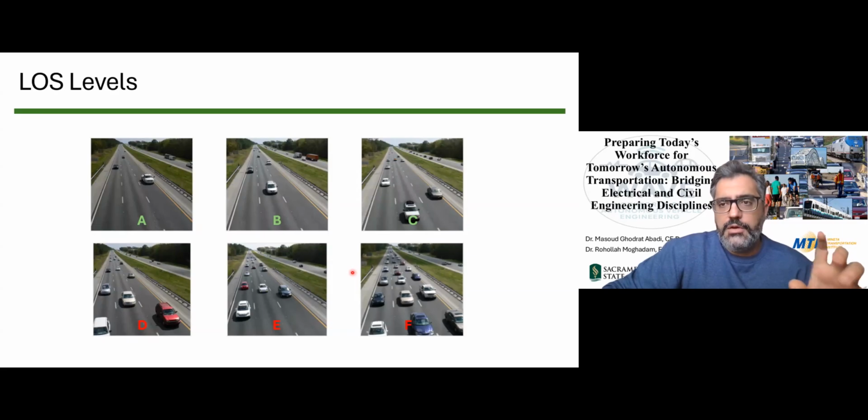With a minor interruption in traffic, like if you are at level of service E, you see lots of vehicles on the roadway, but still the system does not have major queuing. Then suddenly a driver changes their lane, or there is a distracted driver. This will move everything from that uncongested, stable condition to a congested, unstable condition. So level of service F is where we see formation and dissipation of queues again and again.